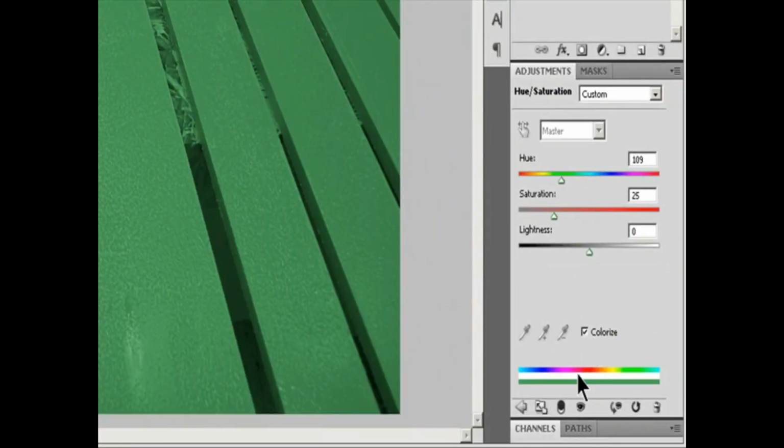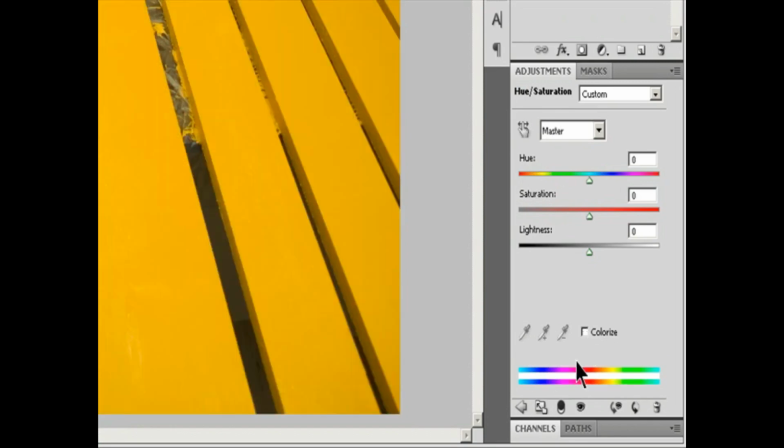4 color wheel values, in degrees, appear in the Adjustments panel. They correspond to the adjustment sliders that appear between the color bars. The 2 inner vertical sliders define the color range. The 2 outer triangle sliders show where the adjustments on the color range fall off. Falloff is a feathering or tapering of the adjustments instead of a sharply defined on-off application of the adjustments.